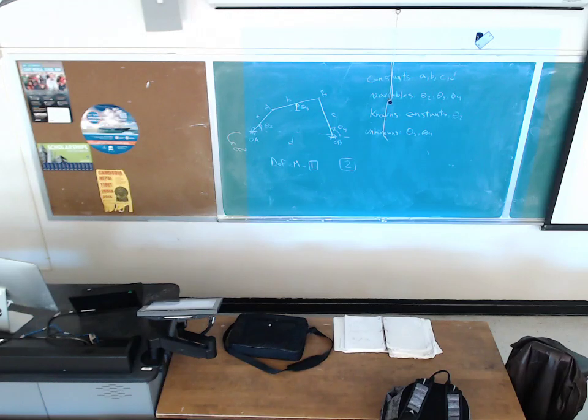So what you can do, we know that link 3 has the length of B. So draw a circle with the center of A and the radius of B. So any point in this circle has the distance of B from the point A. So any point on this circle can be a candidate for the location of joint B. But we don't know where that point is going to be.